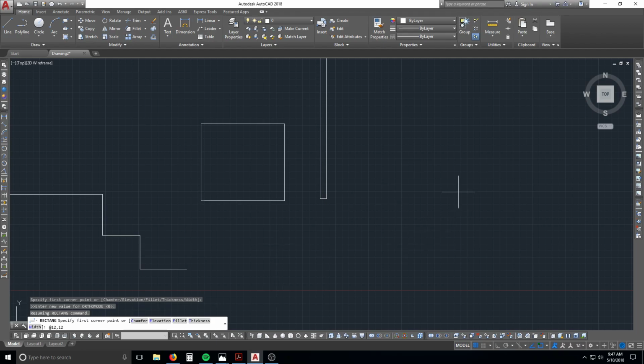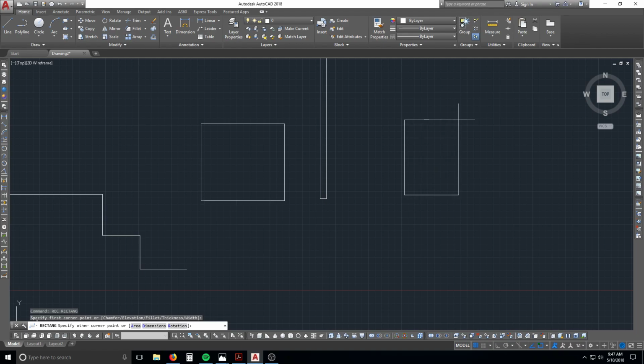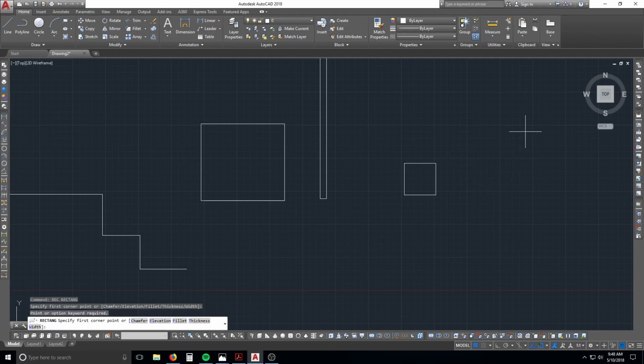Actually, guys, it's rectangle. It's hard to do whenever you're talking. So I'm going to start to draw it first. That was a left click, start, and then drag. I was about to send you down the wrong direction. Now you do type in your shift at 12, 12. Bam, there you go. And again, that's REC for rectangle, enter. Start to draw your rectangle.